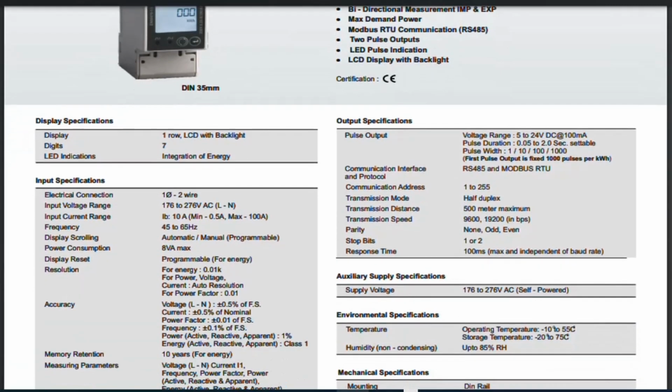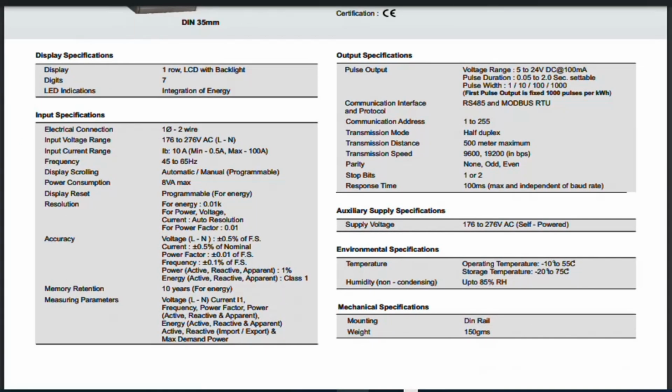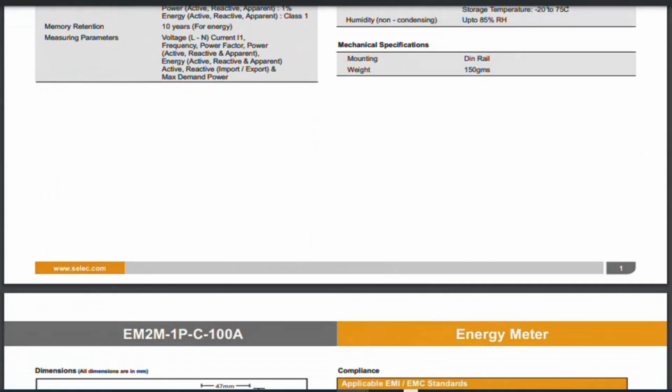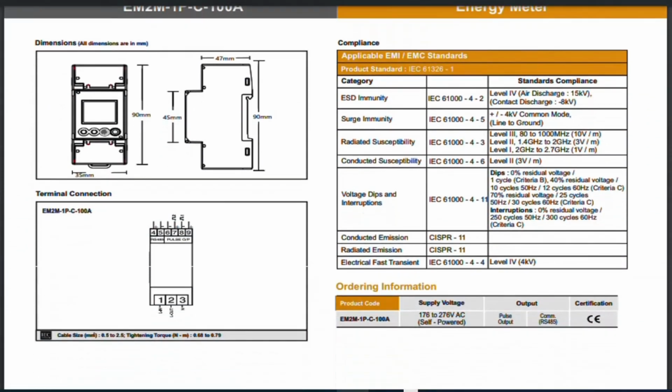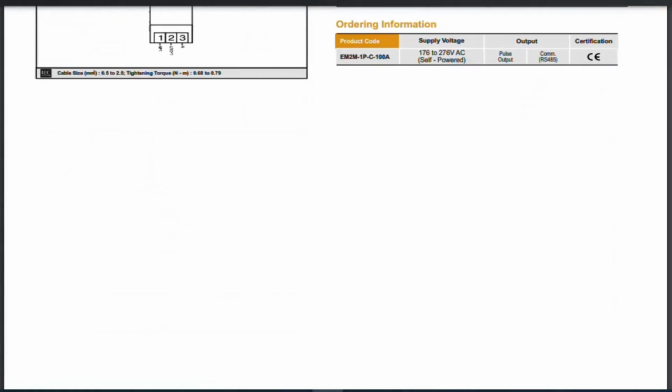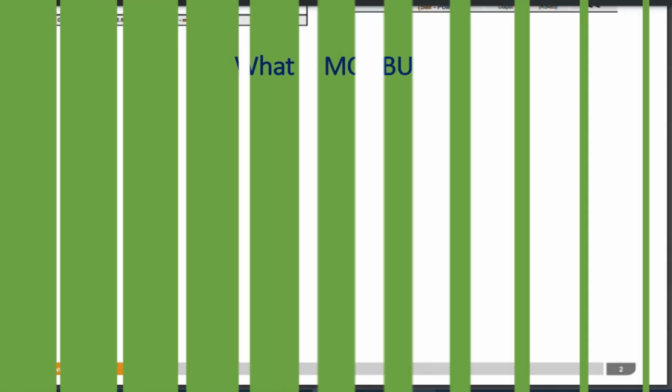The IoT gateway, which reads the data from the meter, will share it to a mobile application or Arduino dashboard to know the electrical usages. The project will measure four parameters: voltage, current, kilowatt, and kilowatt hour. The program can be expanded to read many other electrical parameters, which will be delivered by the meters. But at present, I have limited it to read only four parameters.